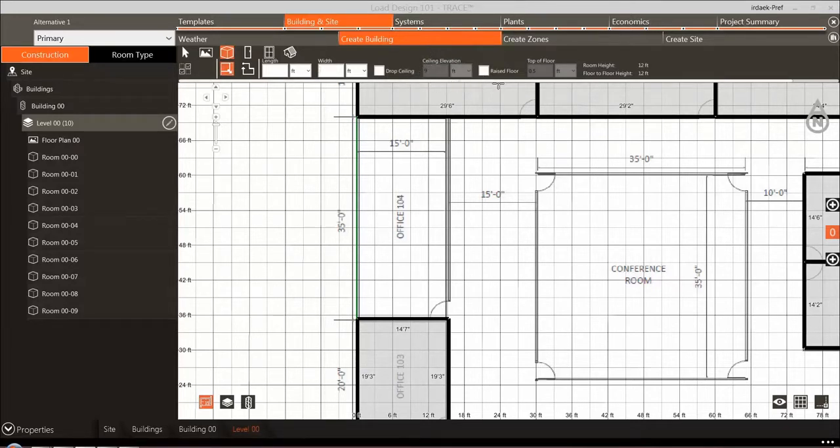the project. Clicking the raised floor checkbox adds an underfloor plenum, and the raised floor height is set by the top of floor field. Be sure to note that you need to check these boxes prior to creating the room in order for that room to have an underfloor or ceiling plenum.